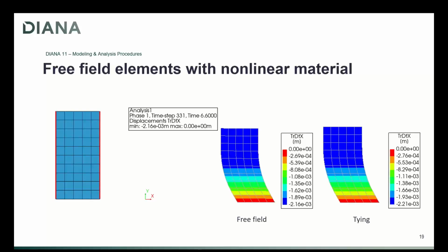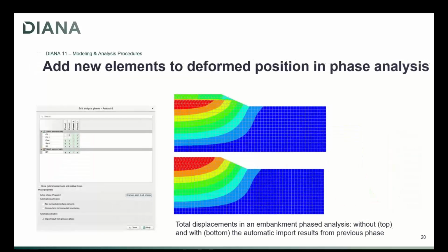And here I'm showing just an example case for the contours of lateral deformation using free field in one model and only tying in the other model. In this comparison, where a rectangle domain with a structured mesh is used, the comparison shows good agreement between the results, which verifies the accuracy. But please note that the capabilities of free fields are beyond this case. For example, when there are arbitrary geometries or when wave radiation plays an important role, then we have to use free field, and tying is not sufficient. Well, this is what is related to my part, and I will ask Tanvir to continue with the rest of the presentation. Thanks.